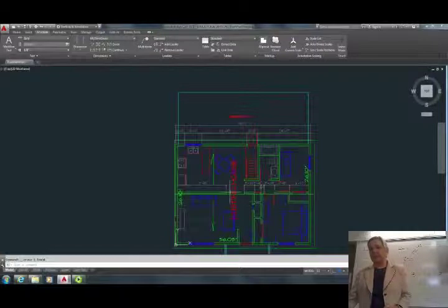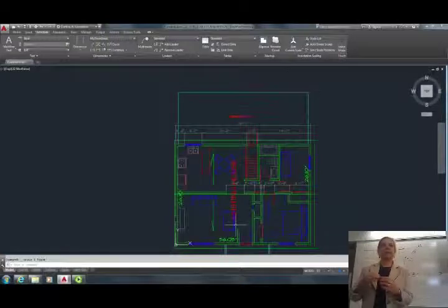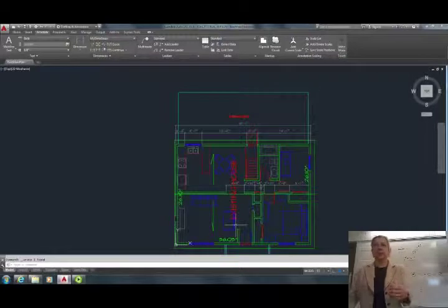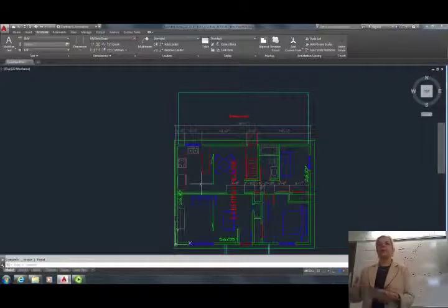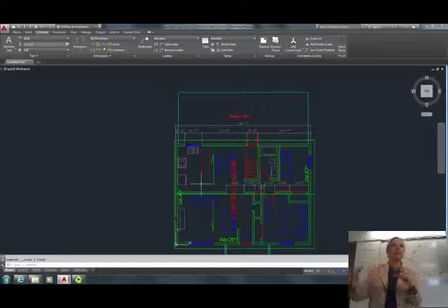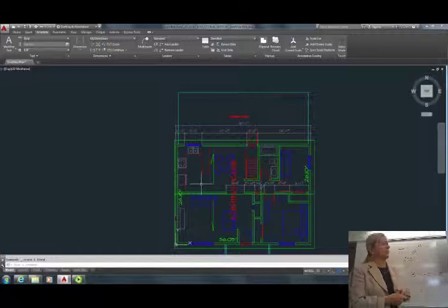These are very important because I have to move furniture, but I would leave the last dimension out in a string so that the builder gives me specified dimensions, and any of the imperfections will happen where it does not matter, 1 inch one way or the other. So if there are specific dimensions on my project, I would dimension them. If I look at your strings and you leave that least important dimension, the leftover dimension, open, I will know that you are listening and you're actually trying to do the same thing.